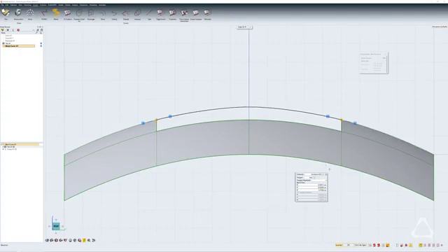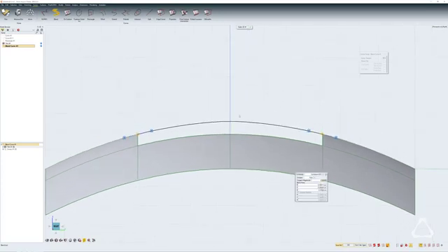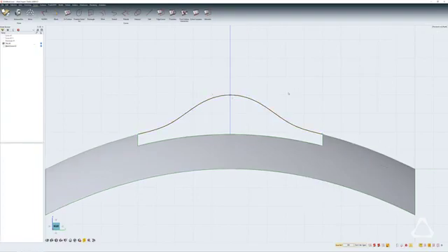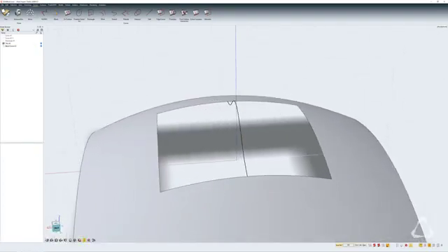to see whatever I like best. Let's leave it at 0.9, and if you want to add a different shape, you just move your mouse to the middle, click and drag another point. Now since the point is free to move, you want to snap it along the z-axis. You can turn on the grid 1 snapping or a grid 2 snapping using alt and 2. So here I can snap it along this. So let's snap it here, right click swipe to complete it,